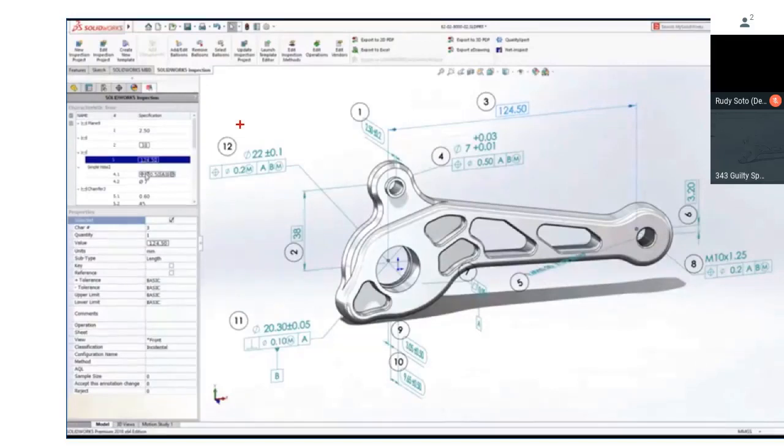Okay, I see them here, like 9 and 10 are actually circled. Correct, that's what they did here, yep. So there's that option in DimExpert. No, in SolidWorks Inspection. Not the circle balloons, but the oval circle. Looks like those were maybe dimensions. Oh yeah, you can do those. Those indicate that those need to be inspected, where the others are just tighter tolerance. Yeah, you don't need to inspect it. You just want the machine to be aware.